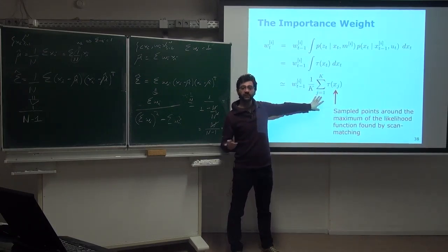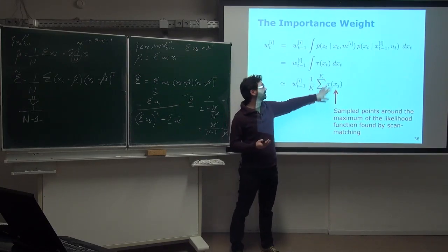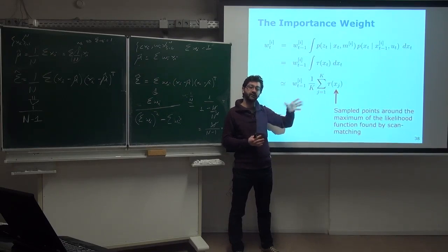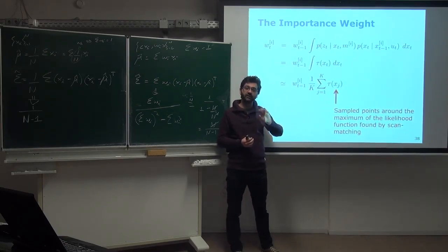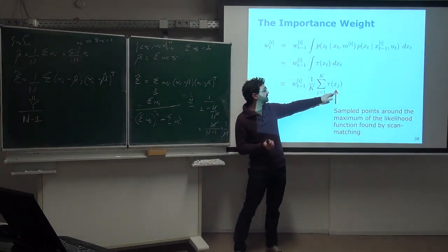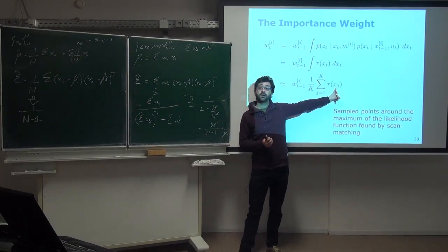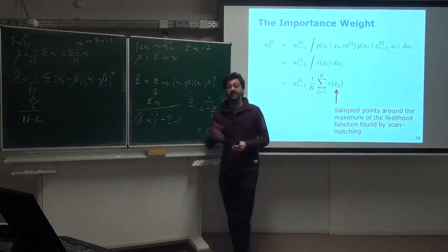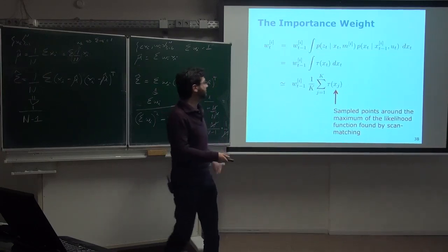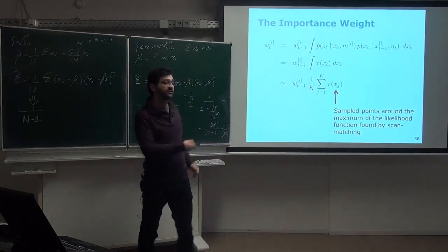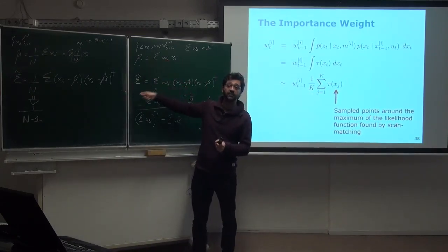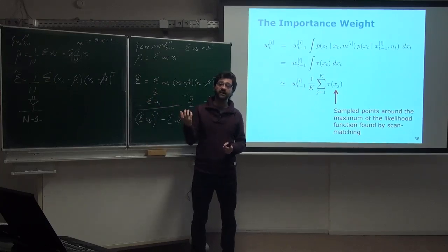It's called the Monte Carlo integration approach. Now, one can do several ways of doing the sampling. This particle filter and the Monte Carlo integral computation are actually very strongly and tightly connected. But the thing that you should consider right now is that we actually already have these samples because we sampled before from the scan matching method, okay? And we can just use the already computed normalization factor for the weights that we used for computing the mean and the covariance before, and just use the same value, okay?